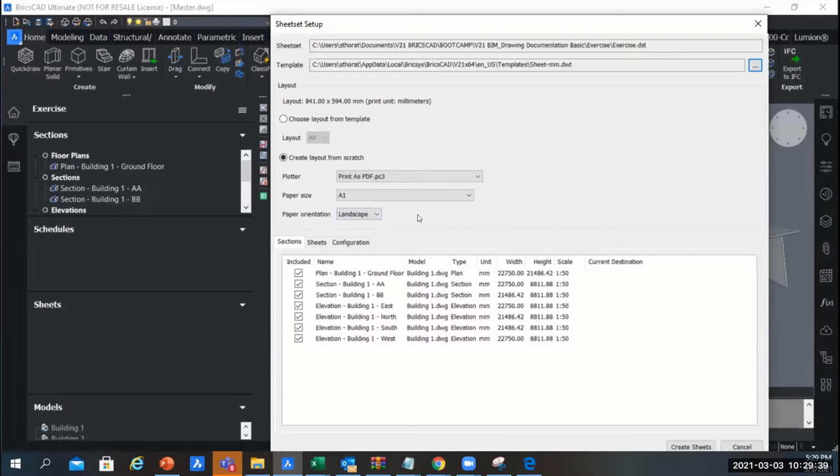So once this is done, then what you can do now is, for example, you go to the sections part below, which is B, which is sections. All of these are the sections that have been either defined by you, or you have BIMified, or they were predefined in the model. You can see all the sections available in the model. You can select or deselect them to be included. So you can unselect and select.